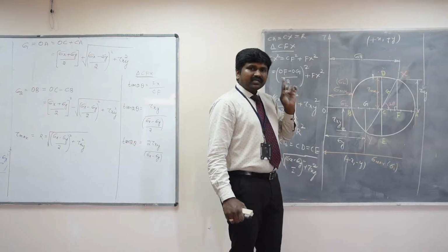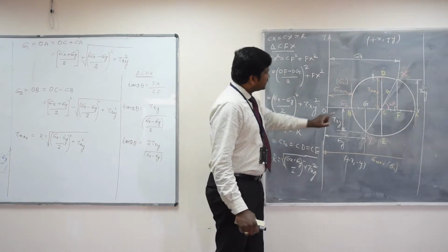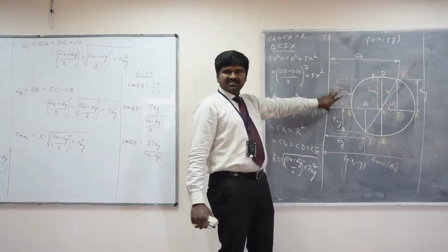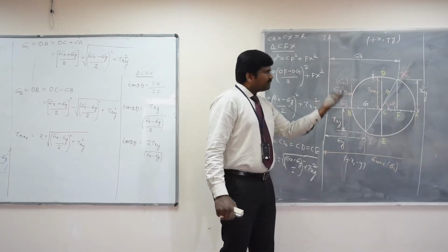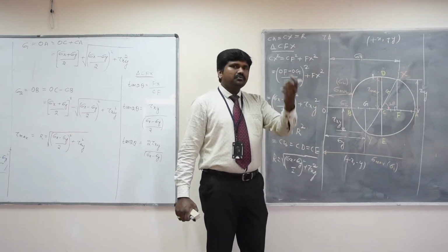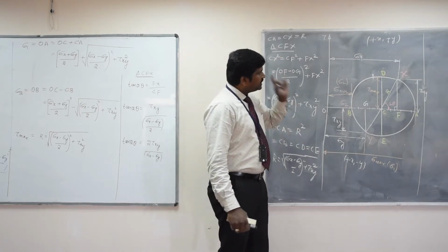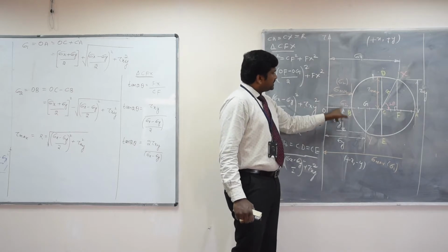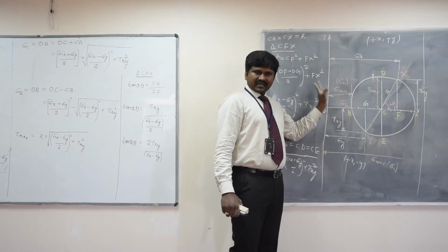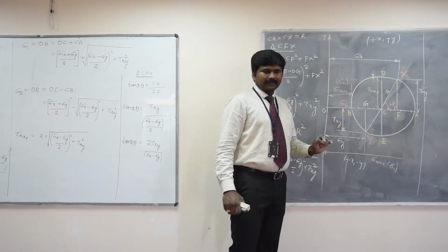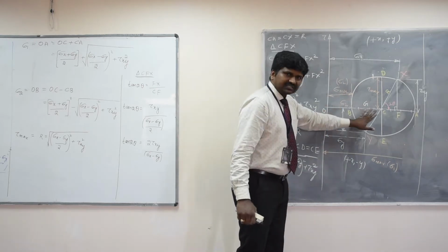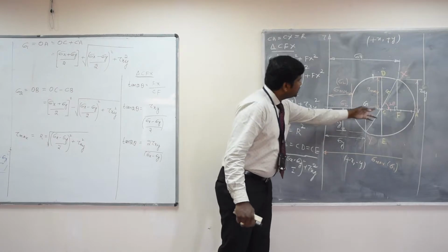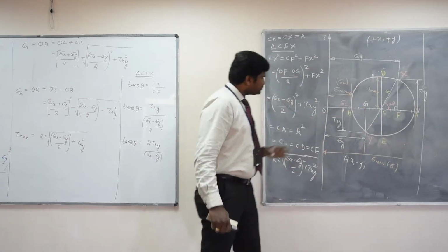One thing you must ensure while constructing the Mohr circle diagram is that the scale of x and y must be the same. That means if you are taking 10 MPa equal to 1 centimeter, the same 10 MPa equal to 1 centimeter you must take in the y direction also. If you take different scales for x and y, you will not get the Mohr circle. Because you have drawn this to scale, you can measure the distance OA and OB, and obviously CD and all that.